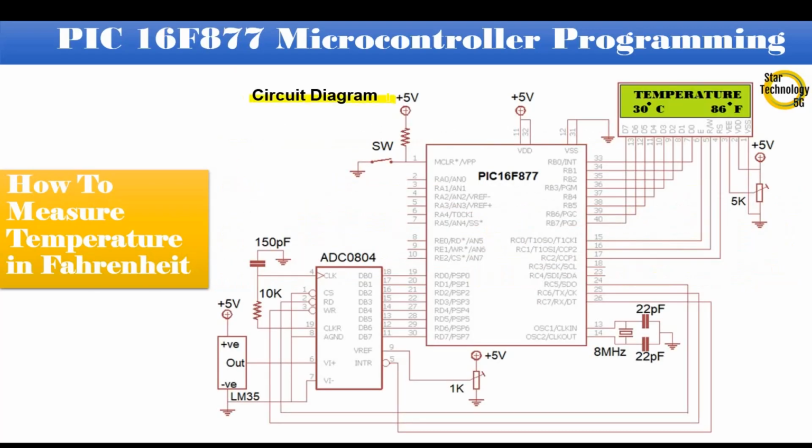Here is the circuit diagram we are using in our project. It is PIC16F877 microcontroller. Pin number 1 is master reset. If we press the switch it will reset the microcontroller. Port B interfaced with LCD data pins. Pin RC0 interfaced with EN pin of LCD. Pin RC1 interfaced with RW pin of LCD. Pin RC2 interfaced with RS pin of LCD.